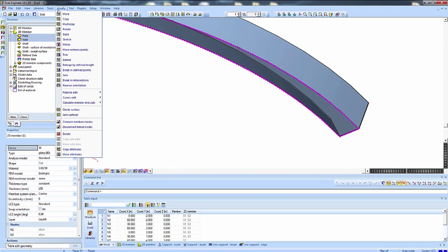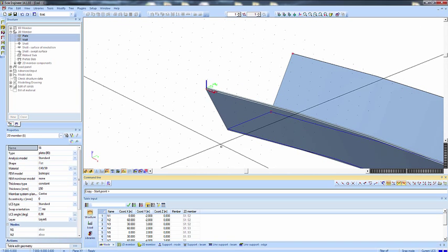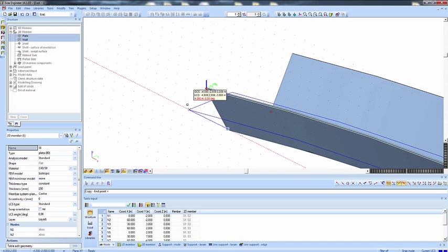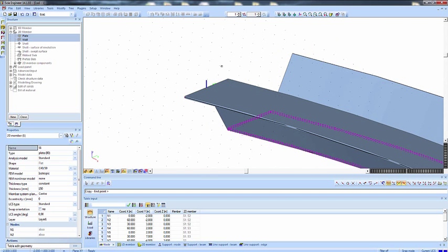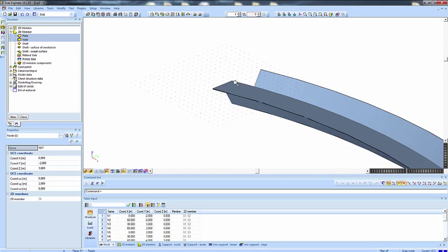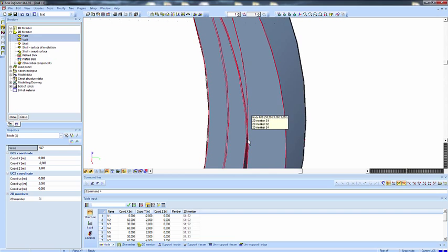What I'm going to do, I'm going to modify, copy it. I'm going to copy it, let's say, from here to there. Copy the add data as well, so in case I put loads and data properties on it, it's going to copy them as well. And I'm going to pick some of the coordinates that define its outline.